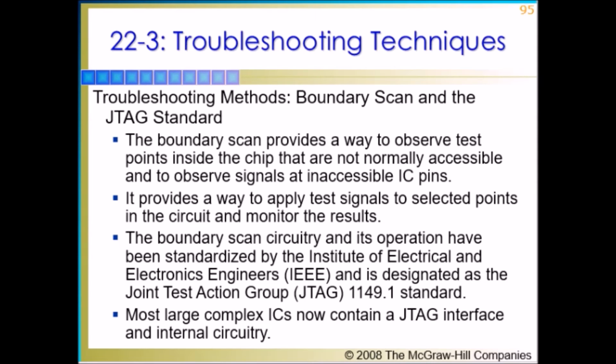The method is called boundary scan. The purpose of boundary scan is to provide a way to observe test points inside the chip that are not normally accessible, and to observe signals at IC pins that are inaccessible because of surface mounting on the PCB.